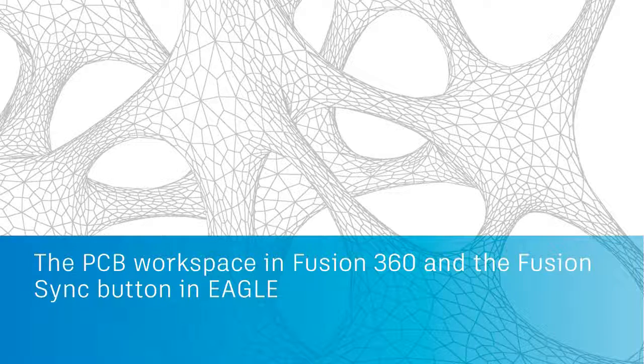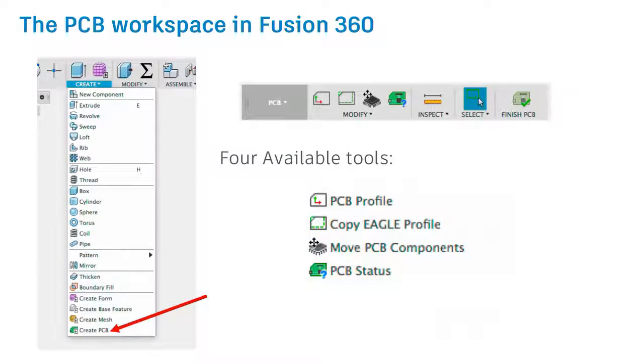So the PCB workspace in Fusion is how we can create PCBs in a Fusion design. And right now, the PCB workspace is relatively simple. We have only 4 tools. We can access these tools in this workspace by using the Create PCB option. It's important to note that you're only going to see that option when you're working with the design history or in parametric mode in Fusion. You won't see it in direct modeling.